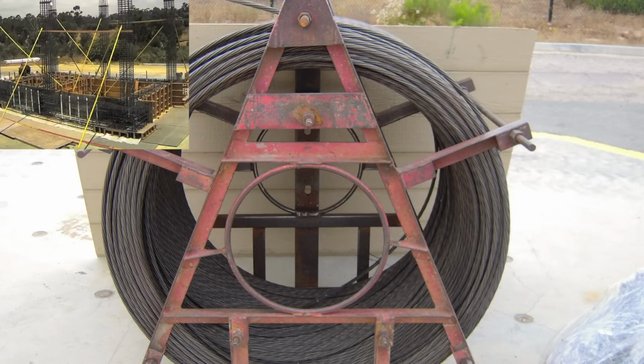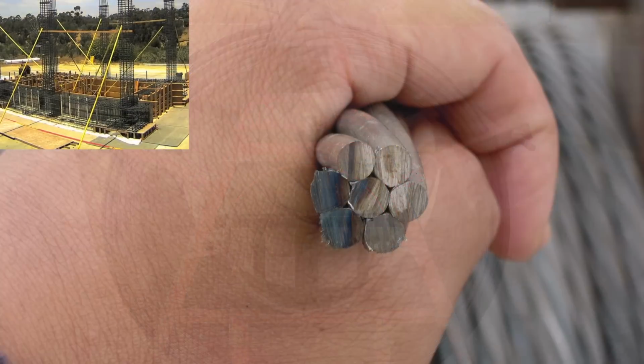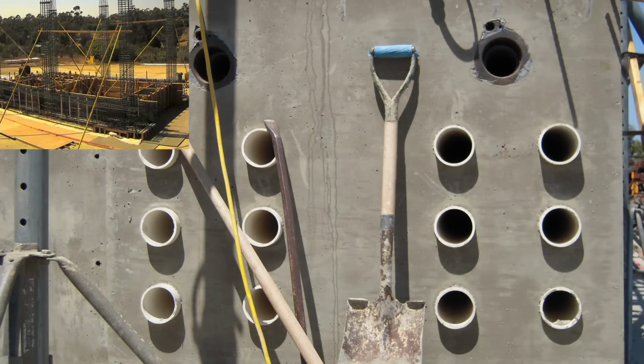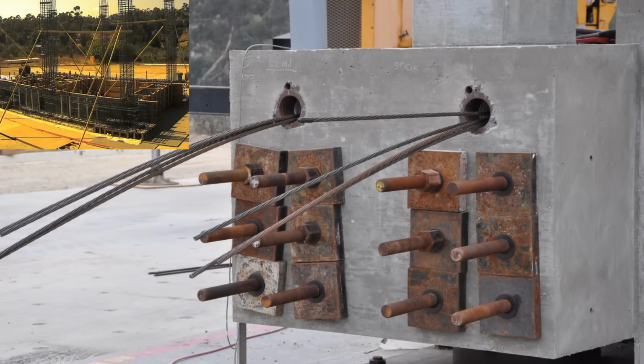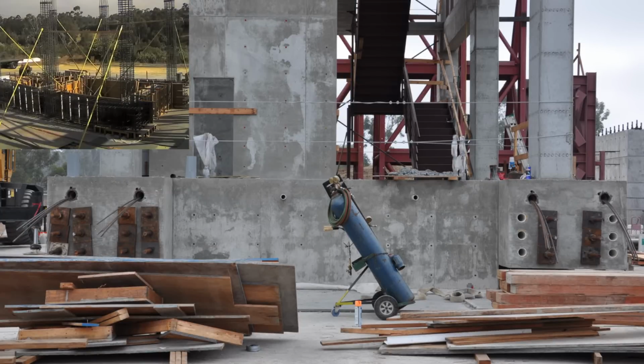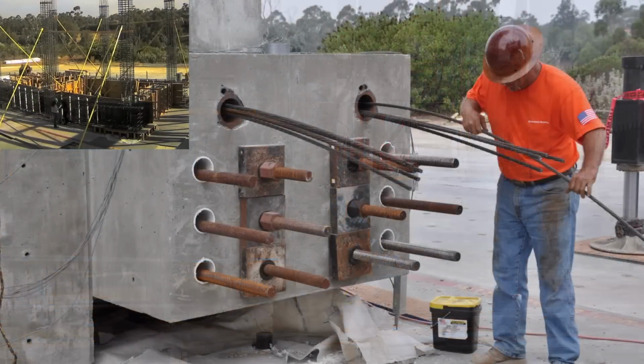In structural applications, pre-stressing using high-strength steel tendons are often placed in conjunction with the nominal steel rebar to improve the strength of the concrete. Two methods, pre-tensioning and post-tensioning, are often used. Pre-tensioning is the placing of concrete around reinforced tendons that have already been stressed to a desired force level. Once the concrete cures around the tendons, the pre-tension cables are cut, thereby transferring their tension forces into the concrete block and ultimately giving it additional compression strength.